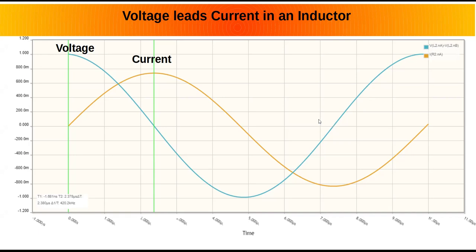But where you put that resistor changes a lot of things. It doesn't change the Q of the circuit, though. I don't think. Well, the Q is determined by the capacitor and inductor, not the resistor. No, it's got the resistance of the RLC circuit. But does it make any difference if that resistor is in parallel with the capacitor and inductor, or in series? It would, because the voltage at those two parallel components is going to be different. So it matters quite a lot, I think.